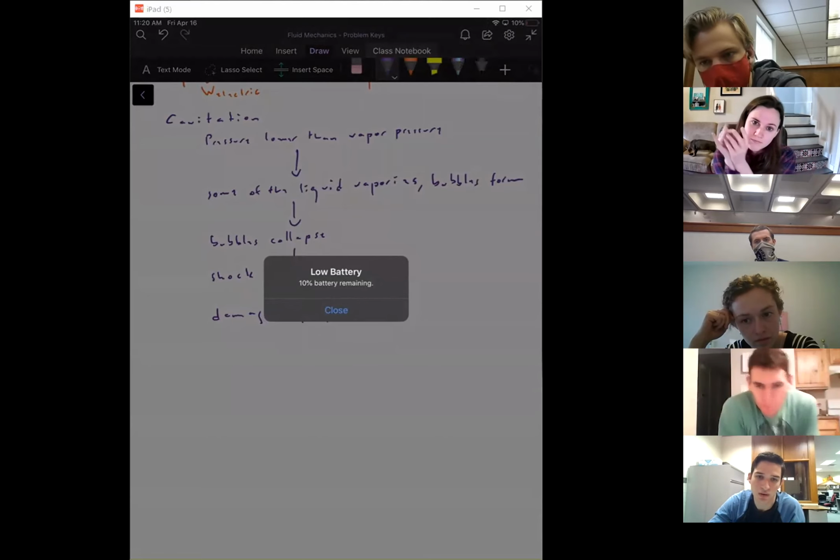So this is the pressure head plus the velocity head. It tells us how much energy we have going into the pump. It is the stagnation pressure, which means that if the velocity goes to 0 somewhere, that's what the pressure will be. It's the energy from the pressure plus the energy from the kinetic energy. So that's the head we have going into the pump, and then you subtract the vapor pressure. Oh, I said vapor pressure, but it should be vapor pressure head. We want this all to be in the same units, the same dimensions.